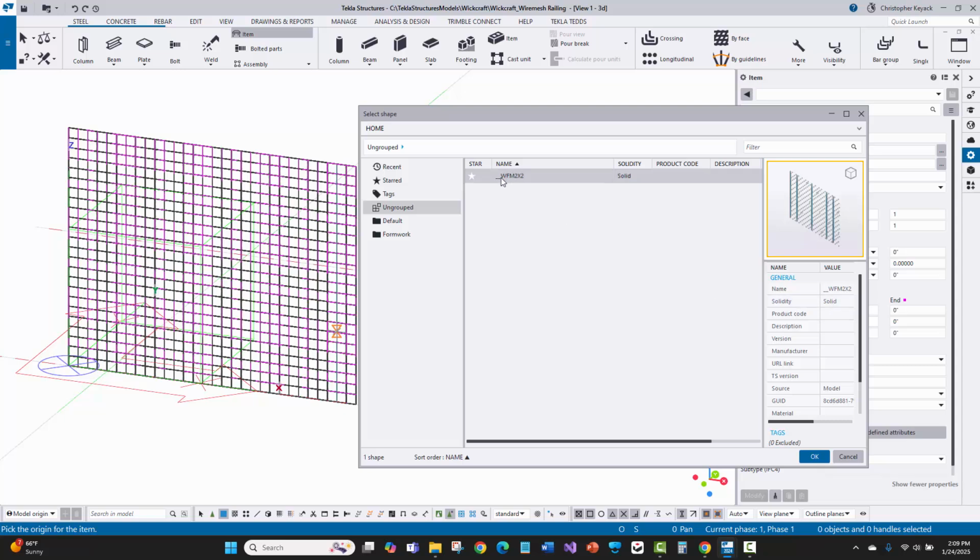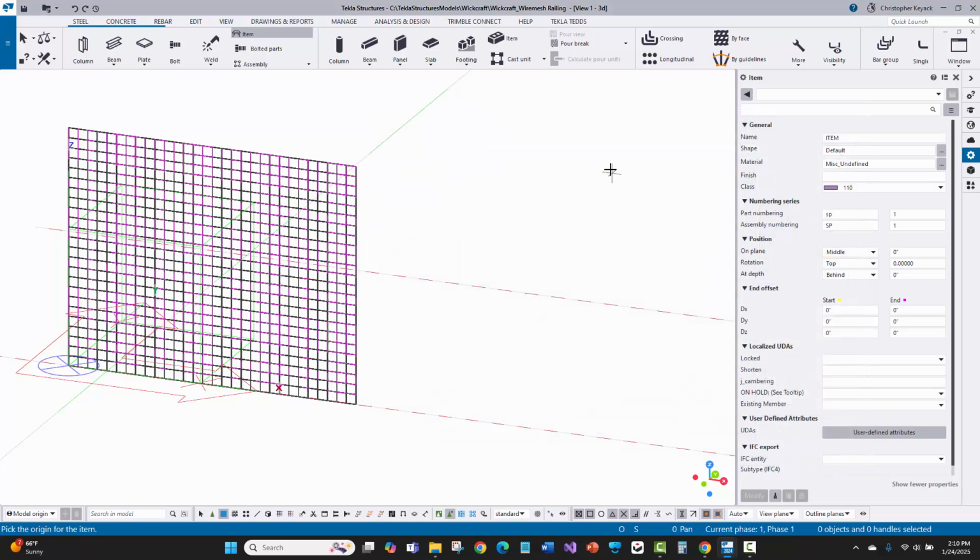Now, the one thing I don't like that it did is it created this, but there's something about shape item creation in Tekla using the native geometry where it tries to read the grid location in the model. I don't know why it does this, but it does do that. And since there were no grids in my model, it puts this underscore underscore here. And unfortunately, there's no way that I know of in the Tekla interface itself to rename that. You can't come in here and rename this or change it in any way. So how do you go fix that?